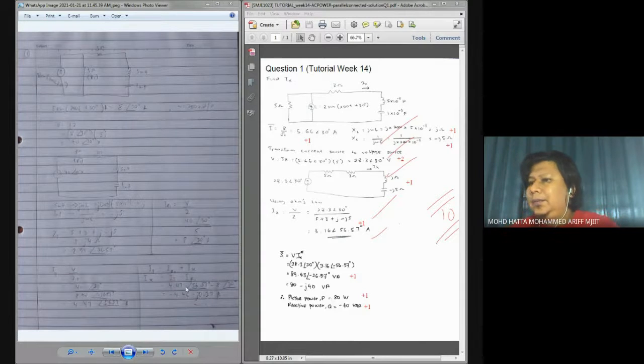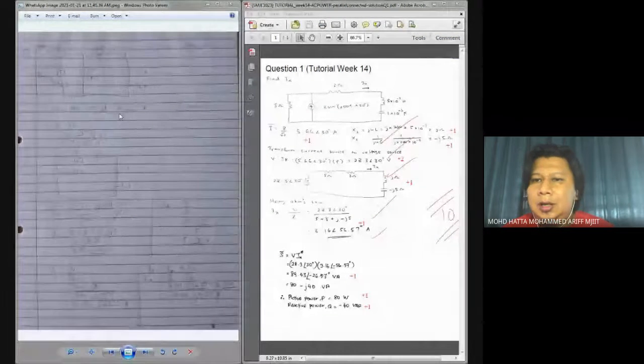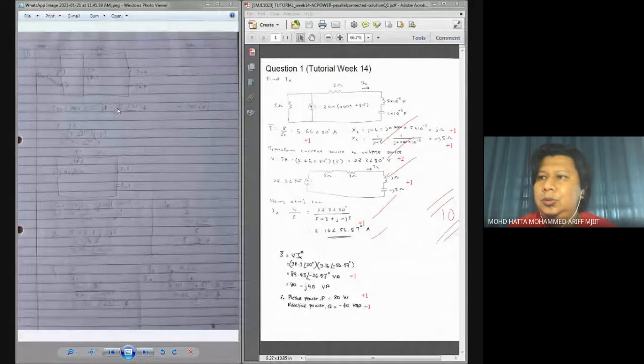All right. Anyway, that's from Hadif. Thank you, Hadif. But next time, please make sure if you try to analyze your circuit, make sure you change the supply value into its RMS value. Don't just put it. I know it is correct, but please do. Please take the RMS value in order for you to get a correct answer for your AC powers later on.